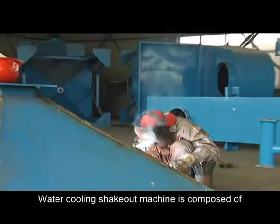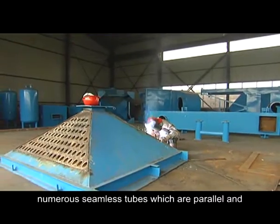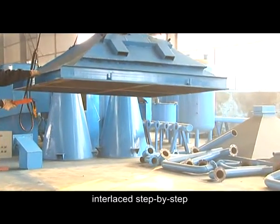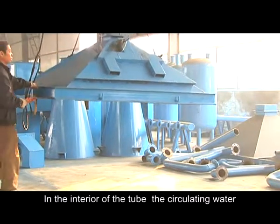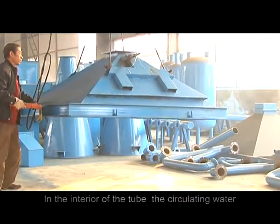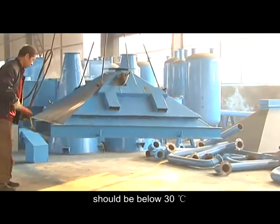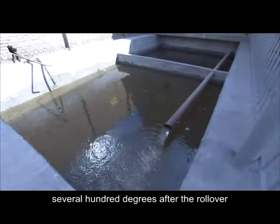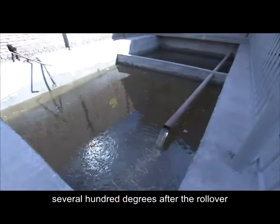Water cooling shakeout machine is composed of numerous seamless tubes which are parallel and interlaced step by step. In the interior of the tube, the circulating water should be below 30 Celsius degrees. It is mainly used for cooling sand that is above several hundred degrees after the rollover.